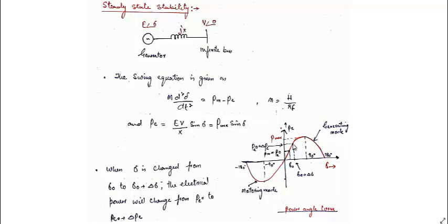from this point to this point. Now the synchronism has again taken place at this point. Mechanical power is now equal to electrical power because delta has increased now. Now I increase the mechanical power again at this point. Now what will happen? The acceleration occurs again and the rotor will start rotating more than the synchronous speed because it is now accelerating. Delta will increase now.